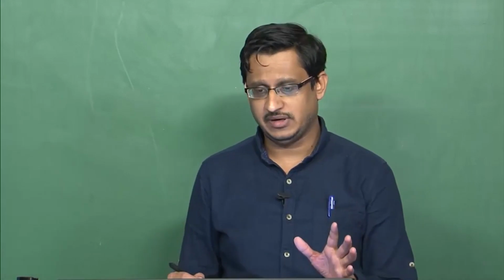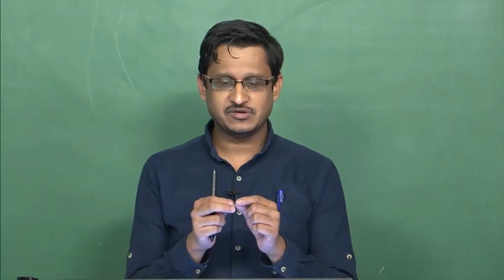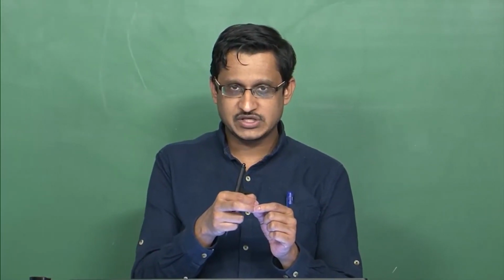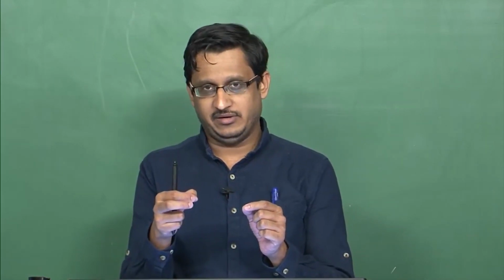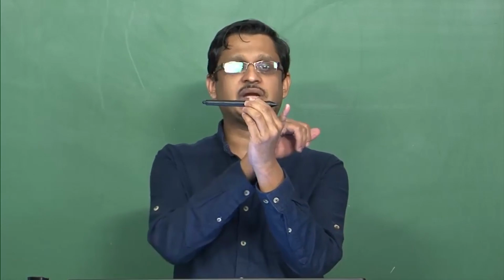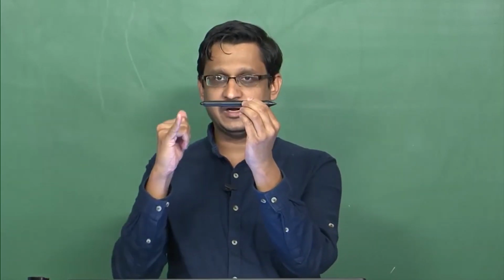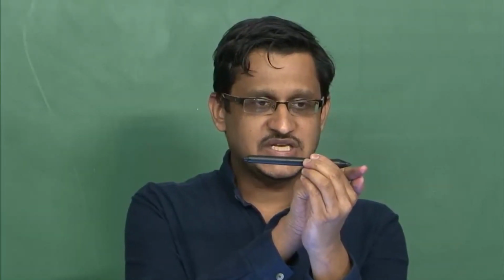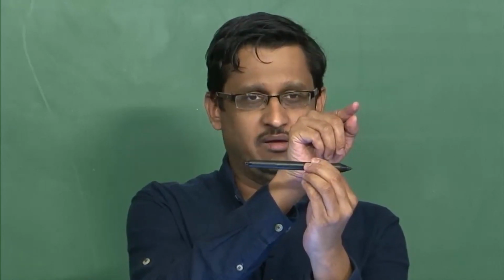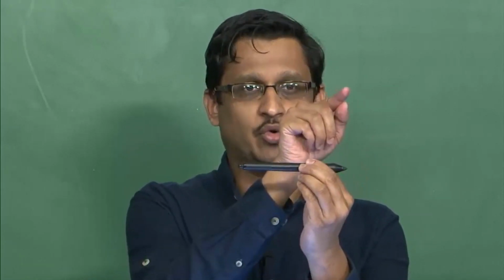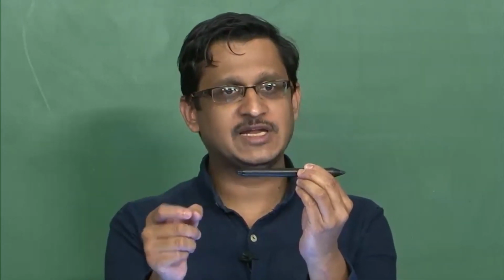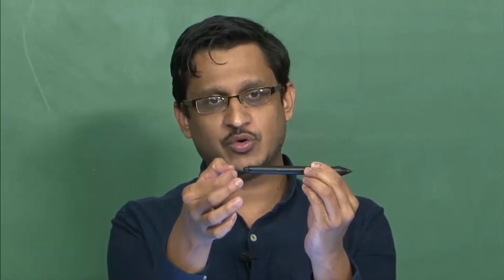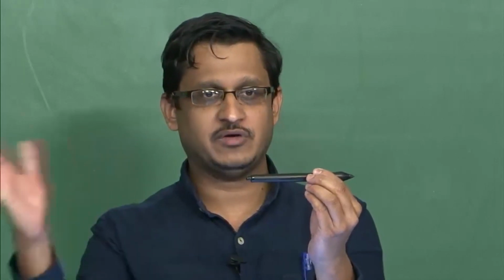You basically understand one thing, right? When we consider a particular piece of wire as a wire, we are not concerned about the time that is required for the voltage at one end of the wire to travel to the other end. That is, if I consider this as my wire which is connecting, say, one integrated circuit here and another integrated circuit at this point, of course it will not be like this, but imagine that way. When the IC changes its state, maybe it goes from 0 to 1, changing the voltage level from 0 to 3.3 volt. If the load has to correspondingly change, if the load is just an inverter maybe for example, then the inverter input voltage must change accordingly, right, so that the output of the inverter must change.